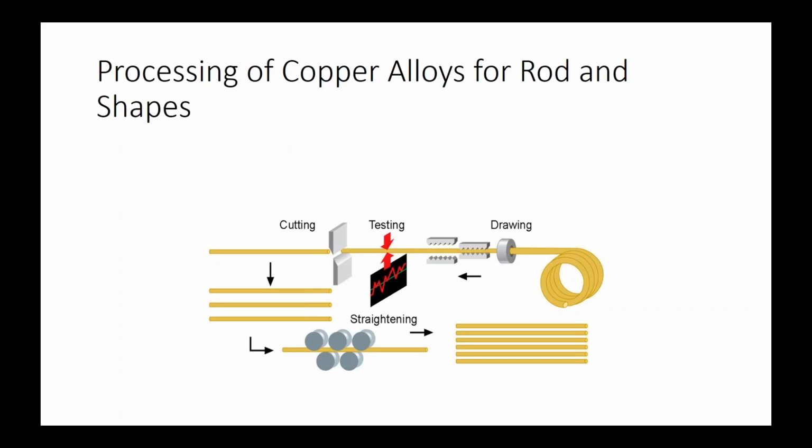At the beginning, you have a composition test in the ladle and or in the furnace before you pour, maybe both. You want to make sure you're pouring the right alloy. You're not pouring a little bit off composition. That can change properties tremendously and be basis for rejection. So that's very important. But because in a lot of highly alloyed materials, you want to make sure you ended up with the right alloy. So a lot of plants will take a cutting or a sample and do subsequent testing to make sure they got the right alloy. It's just checks and balances.